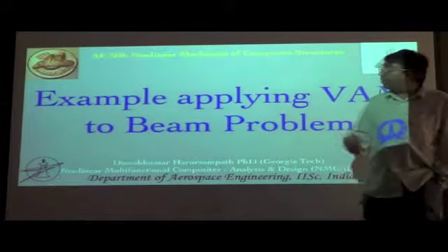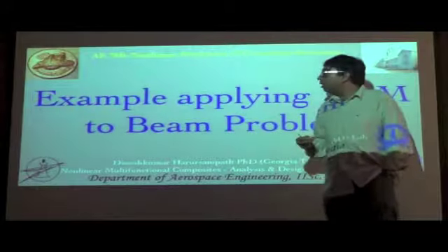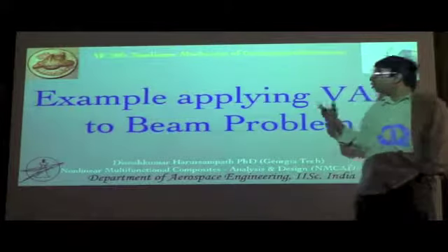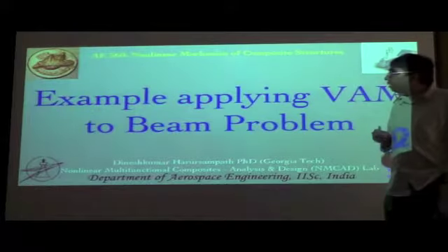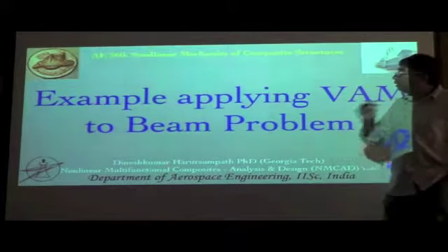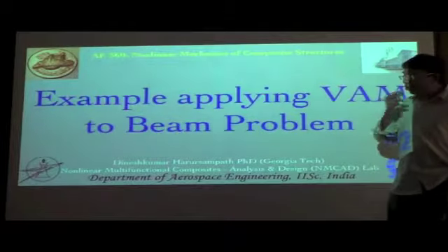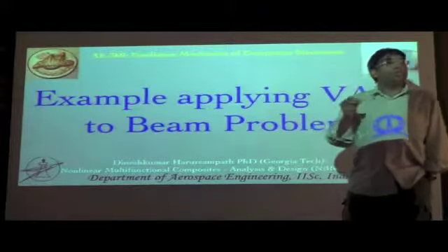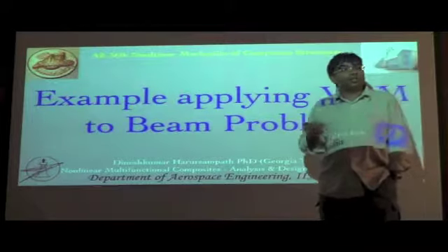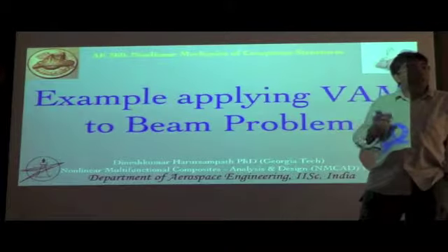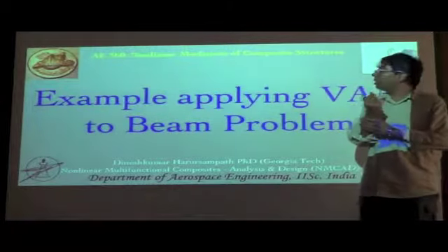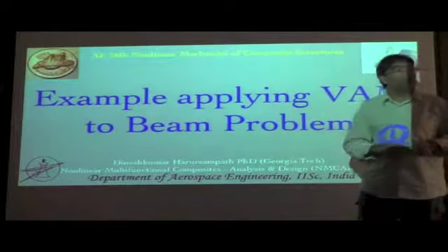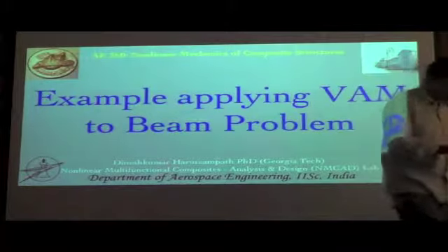We will apply it to a more generic composite beam problem a little later, with initial curvatures in all three directions. That's basically the free twist and the two initial curvatures. But to start with, we'll keep things simple, and let's say we have initial curvature in only one direction. Also we will simplify the deformed configuration: we have a symmetric cross-section about a plane, and the loading is also symmetric about it, and the material distribution is such that all the deformations take place within the plane, and the plane that we will choose for that is the plane of the screen that you have over here.